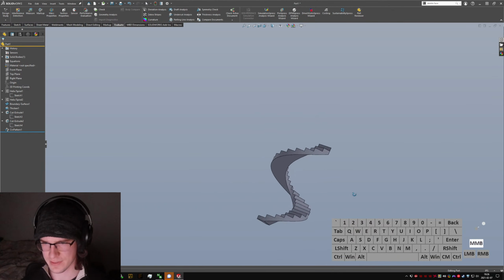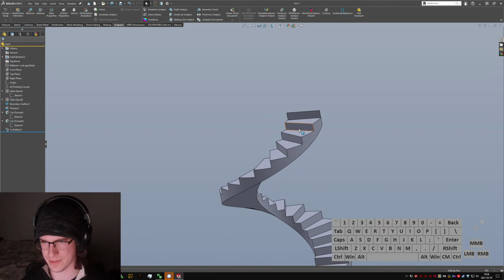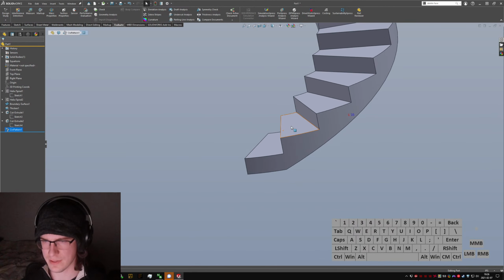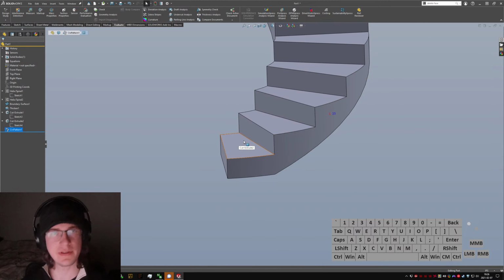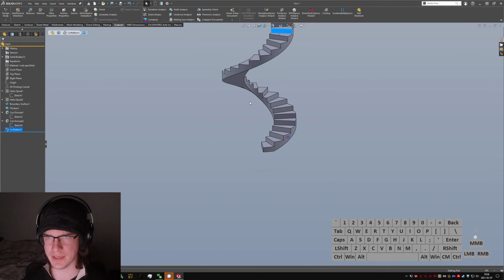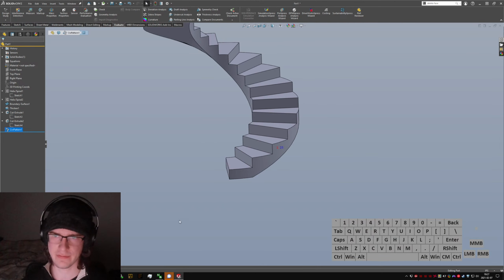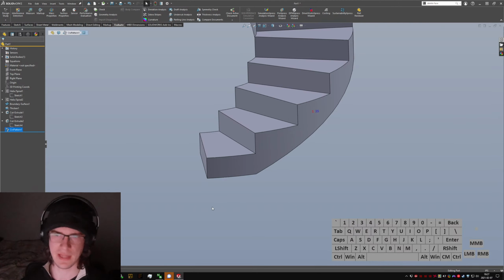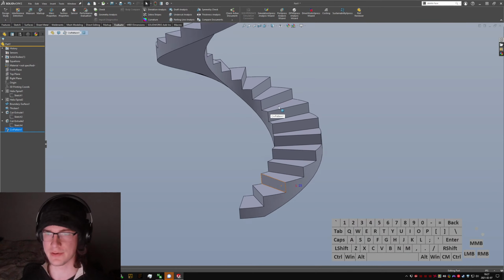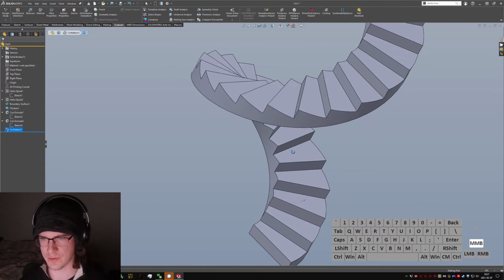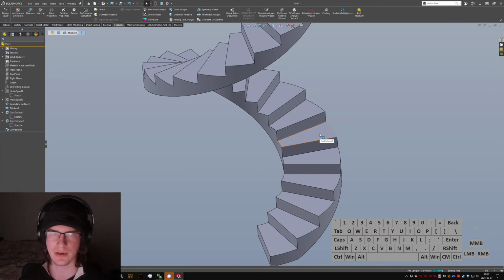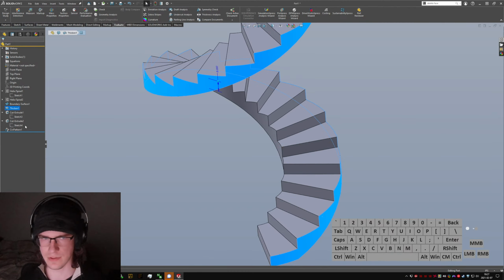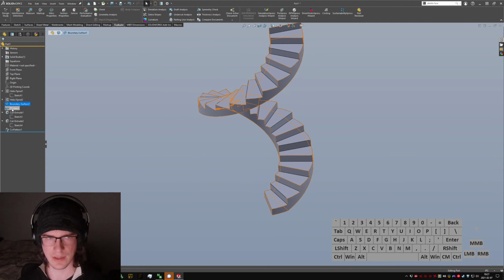Okay, so Solidworks really does not like working with this sort of geometry, or at least in the way that I've done it. The alternative is if you positively extruded these blocks and then patterned them up with the helix and then cut the bottom off using an offset surface, that would also work. Might even be a little bit cleaner just because you'd be more naturally generating these edges, and this outer edge would be circular rather than a cut on a helix or a thickened boundary surface, which makes sort of rough geometry.